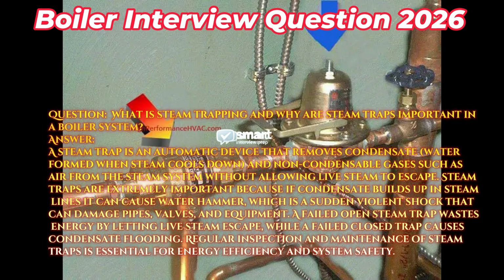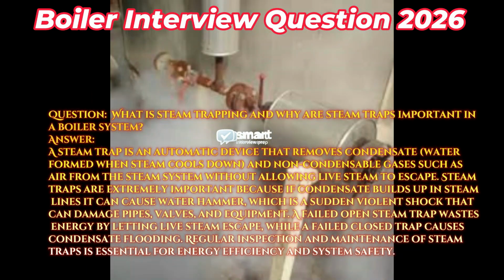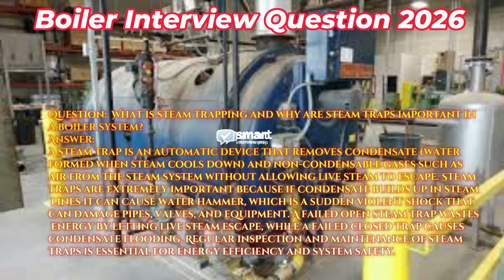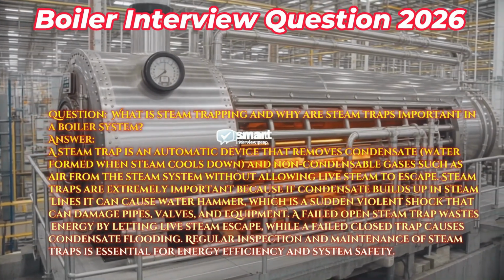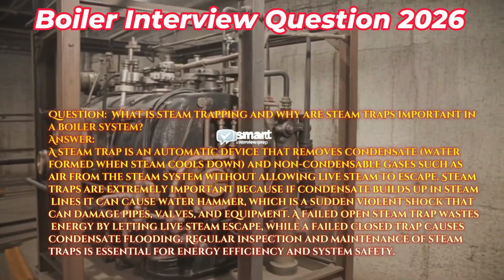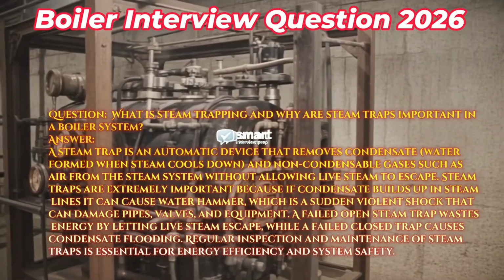Question: what is steam trapping and why are steam traps important in a boiler system? Answer: a steam trap is an automatic device that removes condensate, water formed when steam cools down, and non-condensable gases such as air from the steam system without allowing live steam to escape. Steam traps are extremely important because if condensate builds up in steam lines, it can cause water hammer, which is a sudden violent shock that can damage pipes, valves, and equipment.